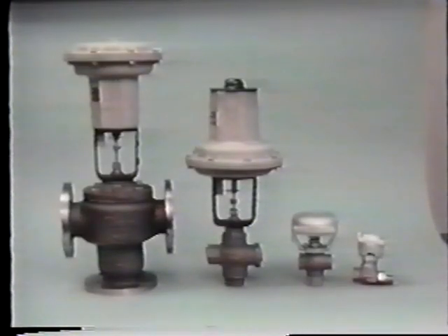Different actuator sizes are available for use with various valve bodies, providing both the necessary action and the ability to close off against system pressure. The larger the actuator size, the greater the pressure drop or pressure differential that the actuator can overcome within the valve body.